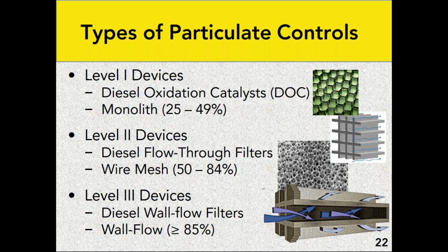Each of those honeycomb openings is a channel that goes from one end of the device to the other. There is no physical block stopping any of the exhaust from going through those channels. The purpose of those channels is to allow for the impregnation of catalytic materials coating the inside of those channels, which produce oxidation that would not happen at the temperatures the engine normally produces.